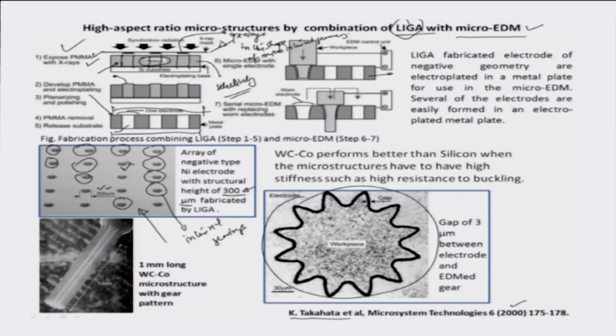The electroplating is done using this substrate here, which is a conducting substrate, that you should always remember. Okay. There is a deposition of platinum along the crevice which has been created here of 300 microns. It is all deposited along this whole crevice as well as on the conducting substrate. The substrate is later removed, as you can see in this particular case, and you have cavities like illustrated here open on both ends, which can be used for further machining.